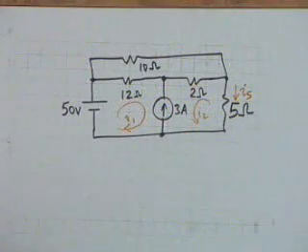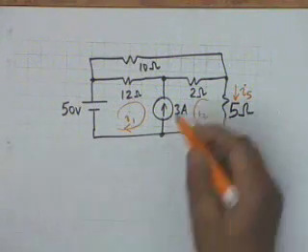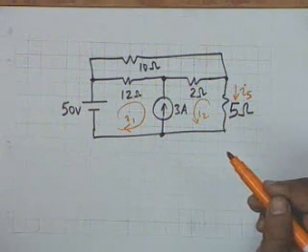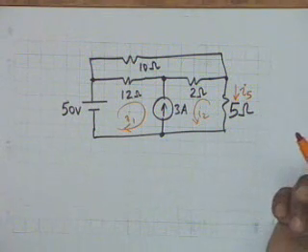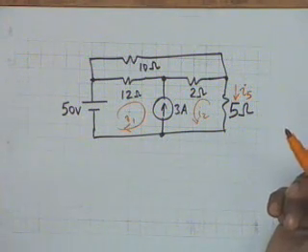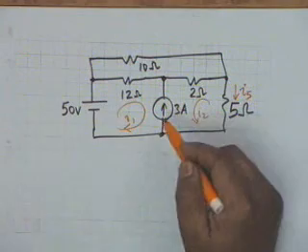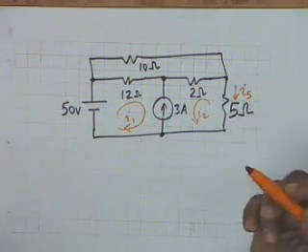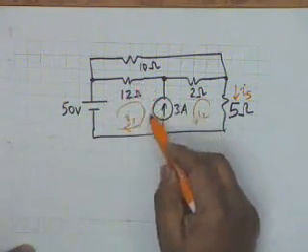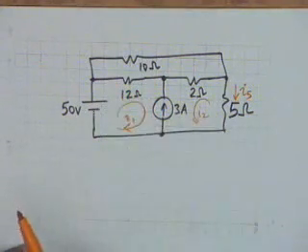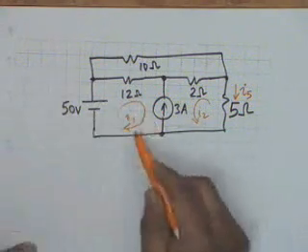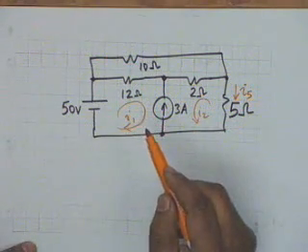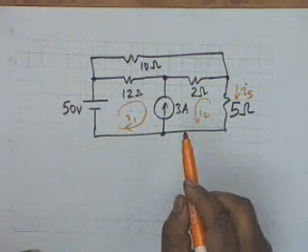However, do you know the voltage difference across this? You don't. You don't know the voltage across the 3 ampere source, because a current generator can deliver a constant current irrespective of the drop across this, and the drop across this cannot be determined by simply looking at the current generator, and therefore you cannot write a loop equation, you cannot write a KVL around this loop. Is the problem clear? You cannot write a KVL around this loop, and therefore the better strategy is that you